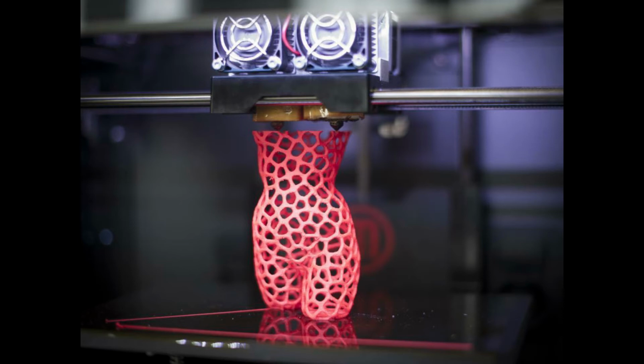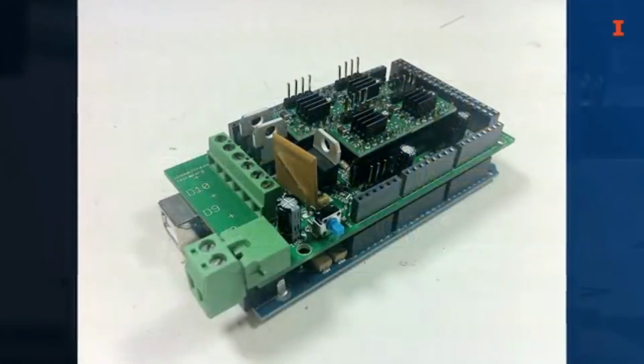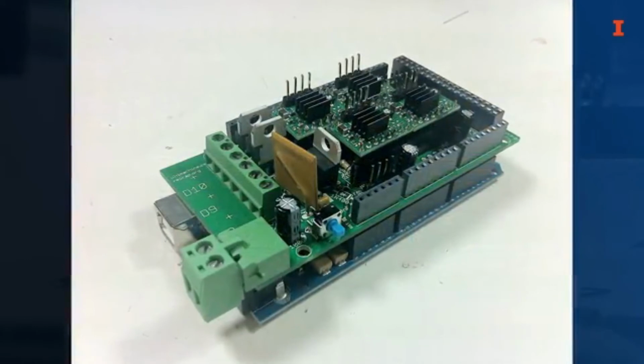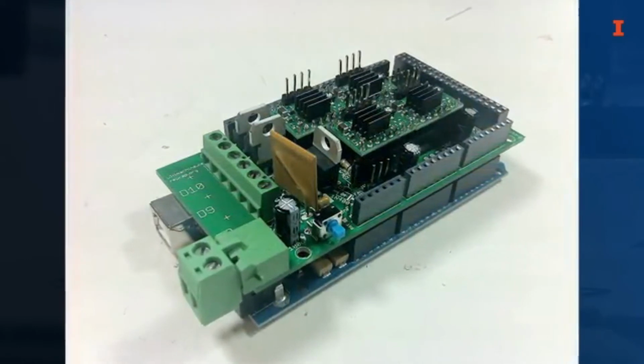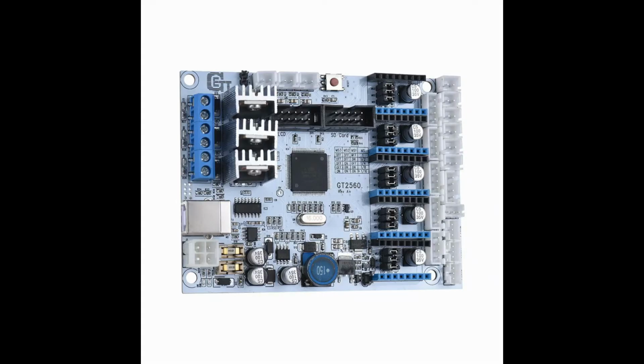For stacked modular electronics, you generally start with a popular and trusted developer board like the Arduino Mega or BeagleBone Black that houses a microcontroller, which is the ATmega in the Mega, and produce a shield to add components and routing to allow you to drive your printer. The stack doesn't have to end there either. You can then add breakout boards and allow your control board to manage stepper motor drivers, extruder controllers, and more.